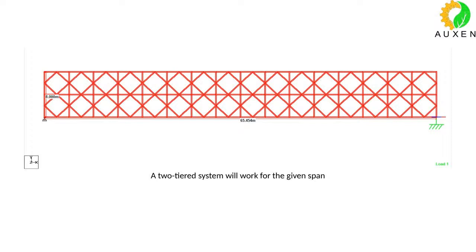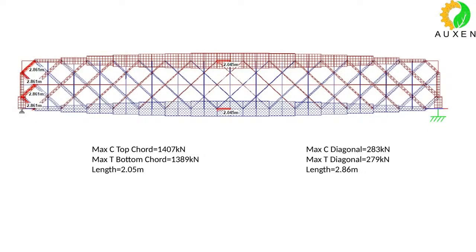My bending moment has doubled up. So the chord forces will naturally double up. So therefore, I have provided two tiers of Bailey's system over here. Okay, will it work? Let's see.